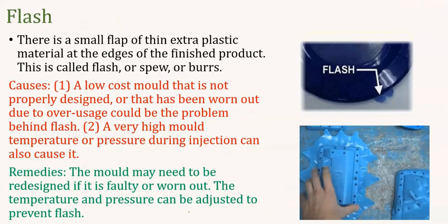And the next one is flash. There is a small flap of thin extra plastic at the edges of the finished product. This is called flash, spew or burst. The major cause is a low-cost mold that is not properly designed or that has been worn out due to overuse.